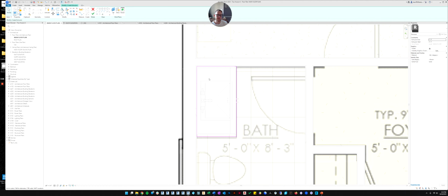The cabinet automatically subtracts the countertop height from the actual cabinet height. So if we picked a 36-inch cabinet, it's expecting the cabinet to be 36 inches tall. So let's put the extrusion, it's going to end at 36 inches tall.